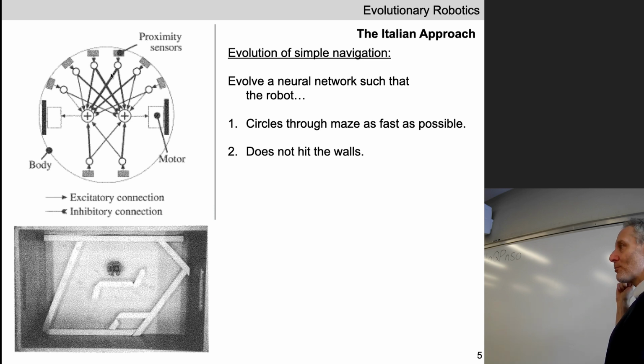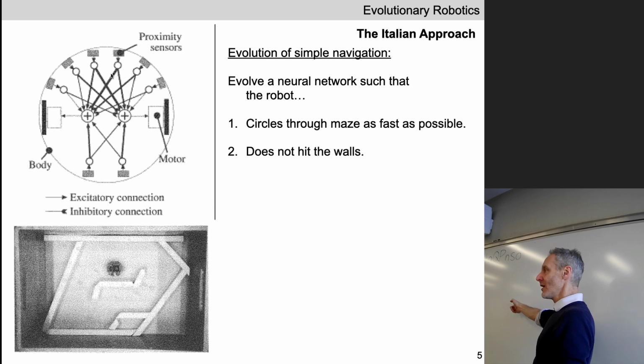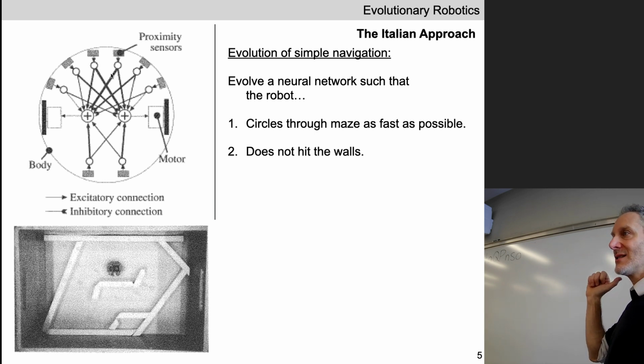It emits a short burst of light, so the sensor can detect the time interval between when the light pulse is emitted and when or if the light pulse is returned back. The further away the proximity sensor is from something, the longer it takes the light to get back.